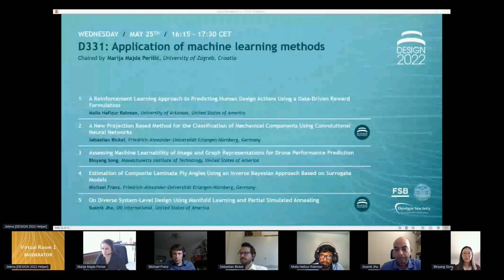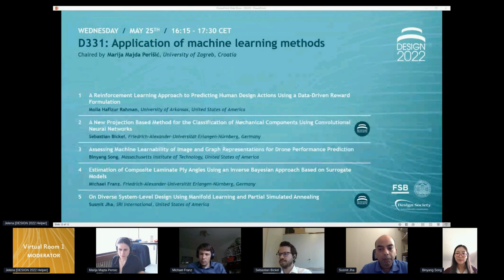Another question is by Binyang, who asks, how are the generated designs evaluated, through simulation or through surrogate models? Right. So Binyang, the final evaluation is done against the simulation model. To be very specific here, we are using Creo, which allows you to do FEA and drag and lift computation. And then we feed that into a flight dynamics model. The flight dynamics model is proprietary, developed over 20-25 years for aircraft design. For the propeller one, it's OpenProp, which is publicly available. So that's the final evaluation model that we're using.